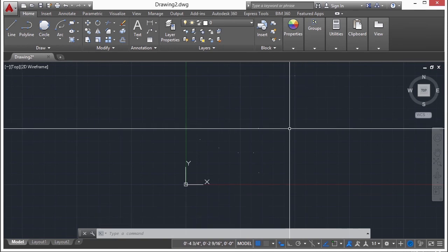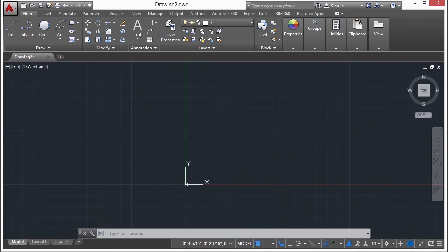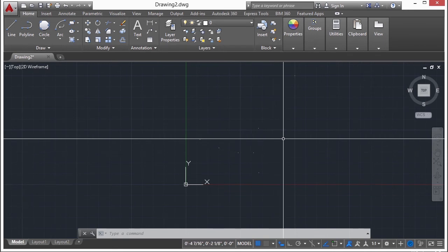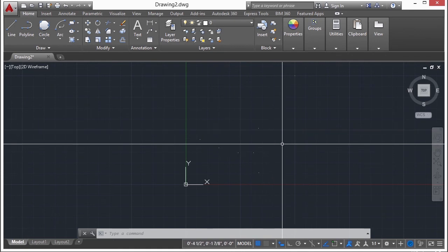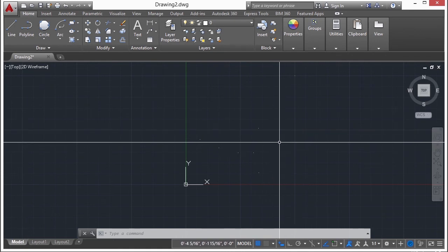Points are also three-dimensional, just like every object in AutoCAD. If you leave the third coordinate off, it will be drawn at an elevation of 0. Right now, these probably look like tiny dots. If not, that's okay. If yours looks differently, then your settings are currently slightly different than mine. But if you've worked right out of the box, they should look like this, and that's okay.